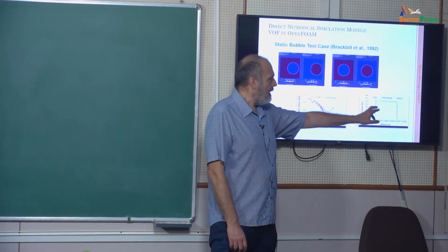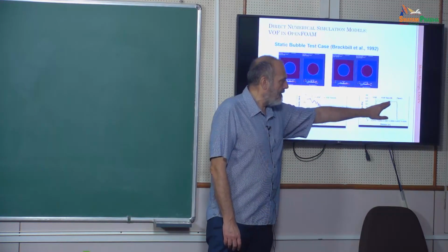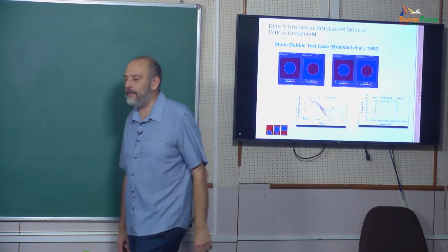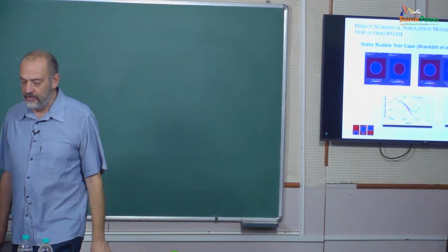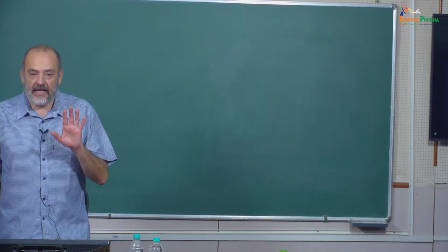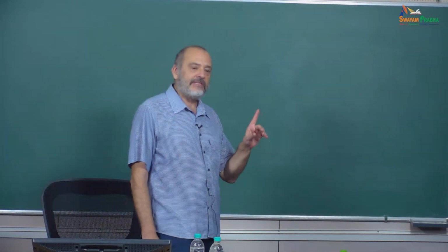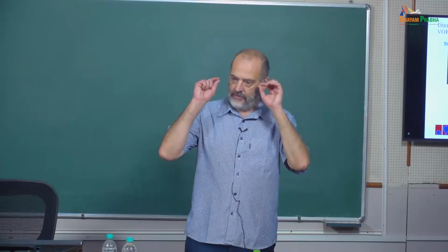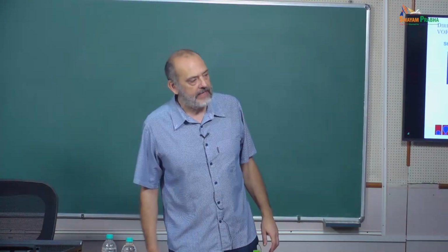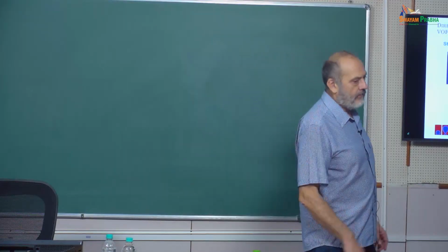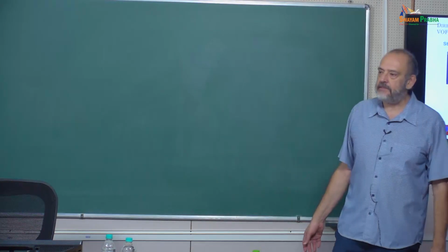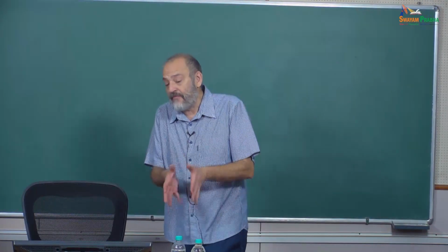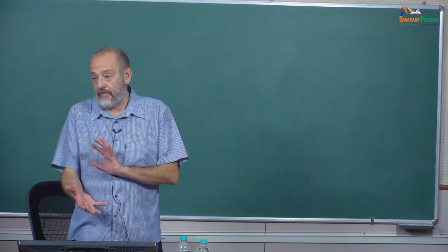The pressure, the theory is the green one, and the capillary pressure is the red and the blue for the smooth and no smooth solutions. And as I said to you, level set is much better in this case. So the capillary pressure that you can get with the level set is good. Okay, we have a problem with the mass conservation, but also here with the VOF, if we are not paying attention, we have a problem with the mass conservation.